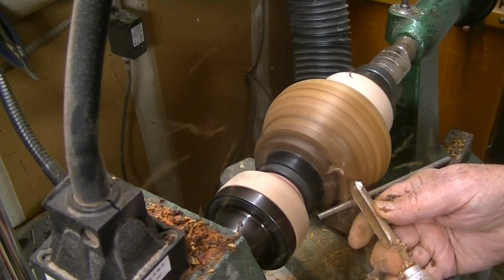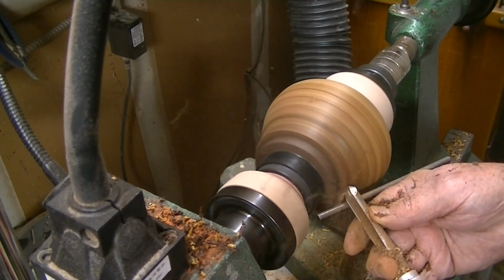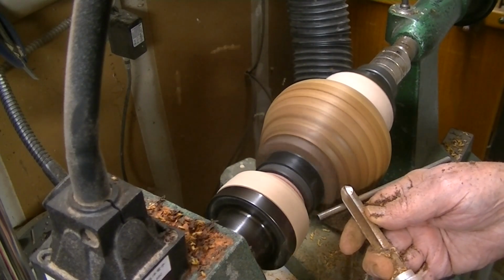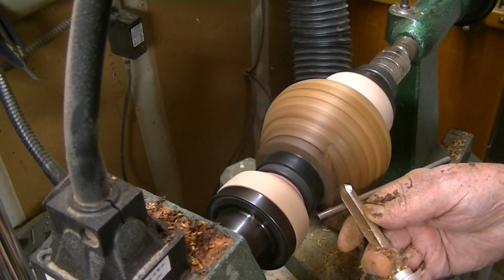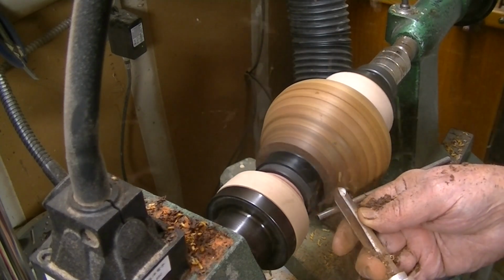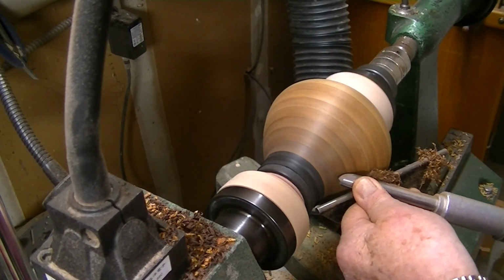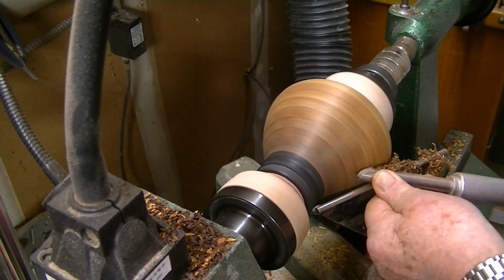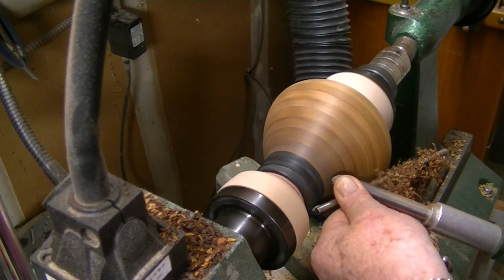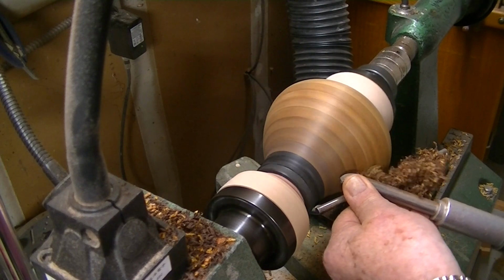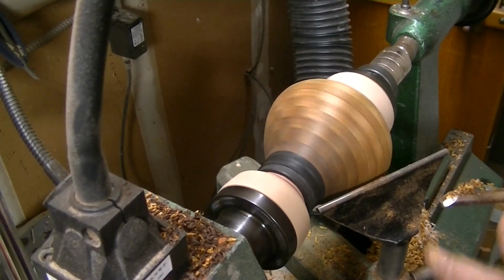Starts tightening up a little bit more towards the bottom because it curves in a great deal. I'm still going to be cautious about taking it in too far. And after a lot of work, we finally got the exterior shape just about perfect. And I've gone to a shear scraping now, which takes off much less material. Gives me a much smoother finish surface on the exterior.